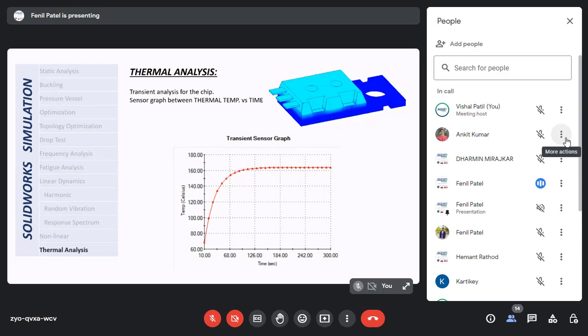And second thing, in ANSYS, you first design in any CAD software. Then you save this model as Parasolid, IGS or STEP, and that file you import into your ANSYS study.